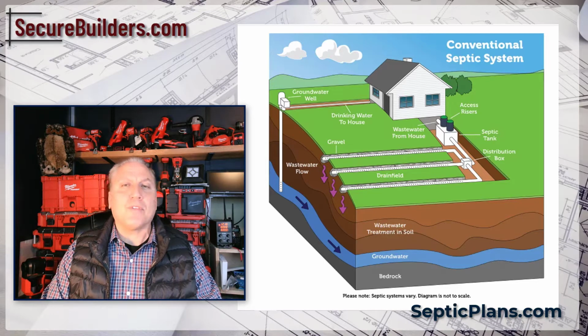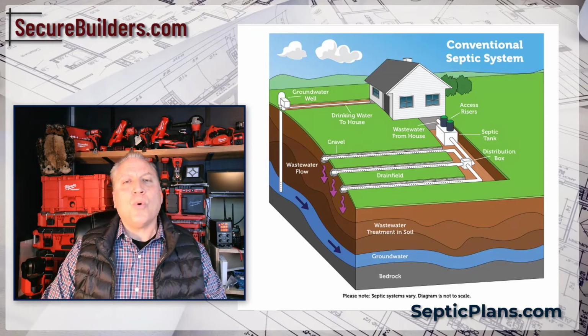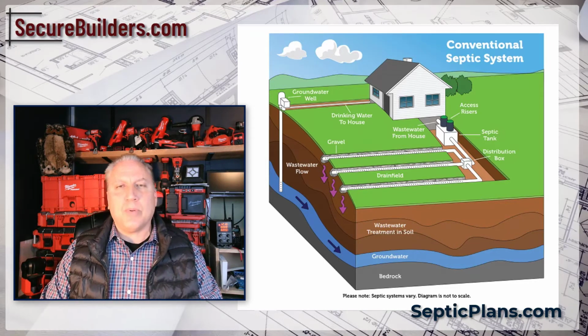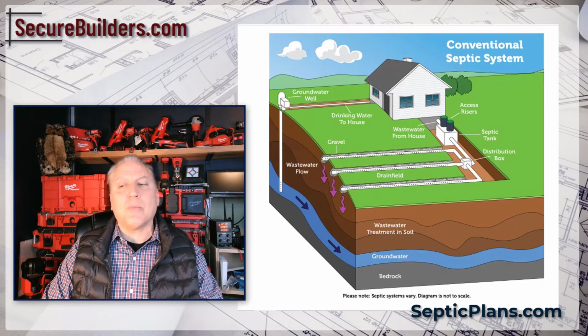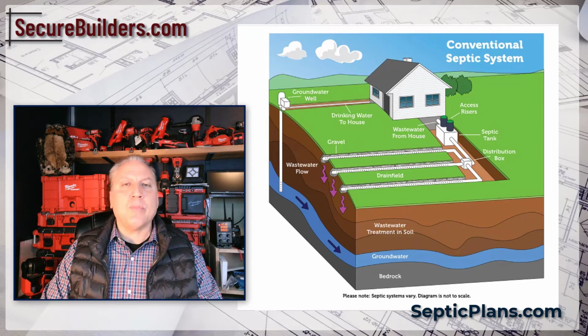But in areas where you have to create a septic, it's very important to create that septic plan in advance of the layout of the house, because if you lay out the house in a way that doesn't allow space for a septic system, you're going to be out of luck. So we're going to talk about septic plans, how to put together a site plan for a property, and how to make sure that that's done in advance.